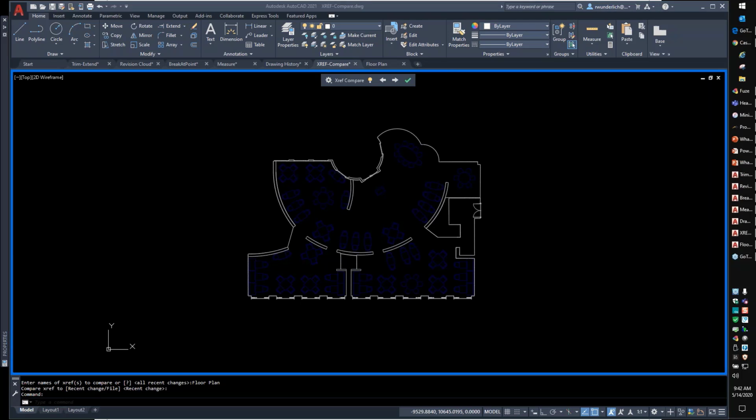Will it pick up geometric changes in object names, i.e. a pipe size change? If it's a geometry change, as far as physical geometry, it will. I have not tried it yet with, for example, a pipe size change in Civil with the civil object enablers, changing a 6-inch pipe to a 12-inch pipe. My guess is it will pick it up because you are drawing lines to represent the inside diameter, which would be a change. If you only draw center lines, it may not pick anything up as far as a change. However, if your label text says, hey, this was a 6-inch, now it's a 12-inch, it will at least pick up your text as a geometry change and let you know.